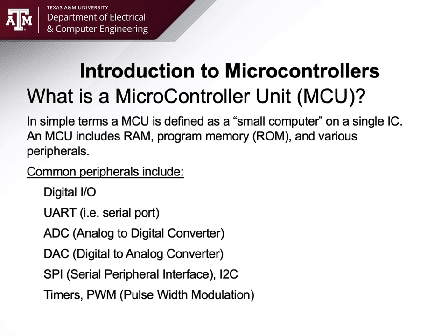So you use something like the SPI bus, the serial peripheral interface, which was invented by Motorola, and then you have the I2C bus that was invented by Philips. Philips trademarks I2C, but it's a really common data interchange format, and a competing technology that uses the exact same protocol and bus format calls itself the System Management Bus, or SMBus.